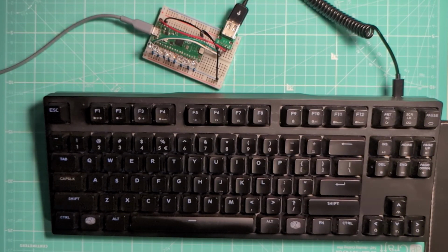As you may know, GPIO pins can be set as both inputs and outputs on HID Remapper mappings. When set as inputs, they can be used for connecting external buttons or switches, and when set as outputs, they can, among other things, be used for driving LEDs. Let's make a words per minute meter for our keyboard using HID Remapper and some LEDs.